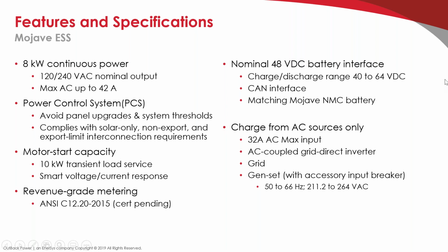And what this does for you is it allows you to modulate the inverter down using the included CT so that you can tell it, make sure that this CT never sees more than 7 kilowatts from the inverter, or 4 or 3.5, or whatever the number happens to be. And that allows you, because of that certification, to size your overcurrent protection and your wiring accordingly. So you don't have to size it for the maximum the inverter can put out. You can size it for what you've told the inverter it should put out.